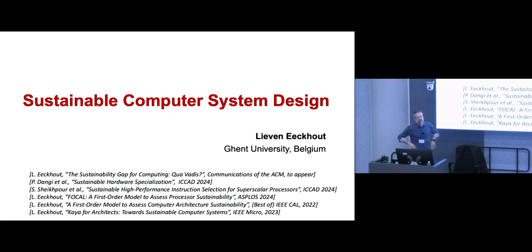Regarding, maybe related to the previous but one question, about the domain-specific accelerators and replacing them with FPGAs. I guess what I was thinking was, if you had several applications running concurrently, and collectively they're going to be using maybe a large proportion of the 40 or so DSAs you would have had, is that feasible? I don't know how quick these things can be reconfigured. Presumably you can't reconfigure every context switch or anything like that. Yeah, there's definitely a cost associated with reconfiguring reconfigurable logic, CGRAs or FPGAs.